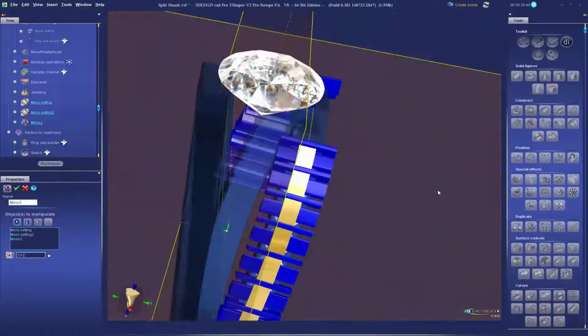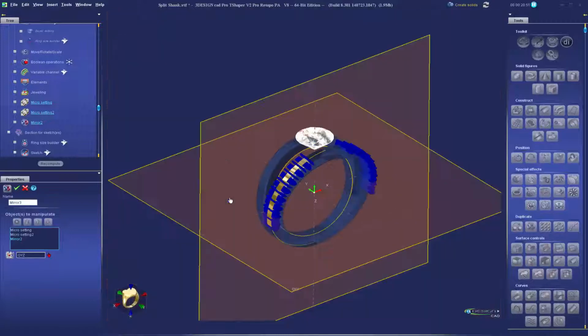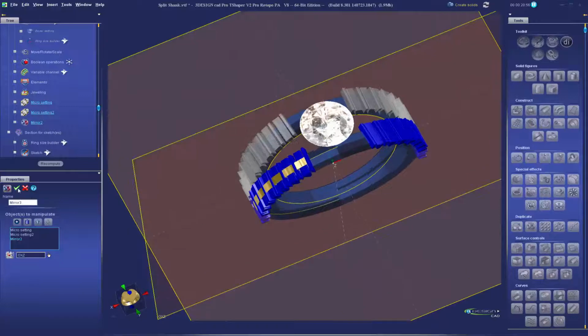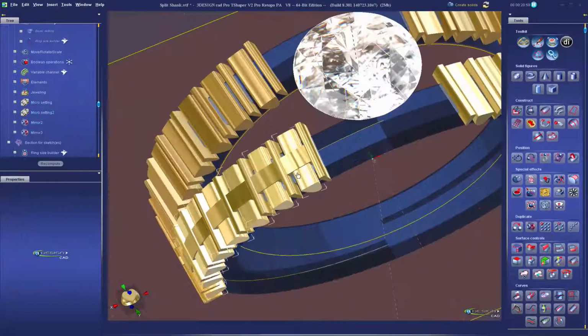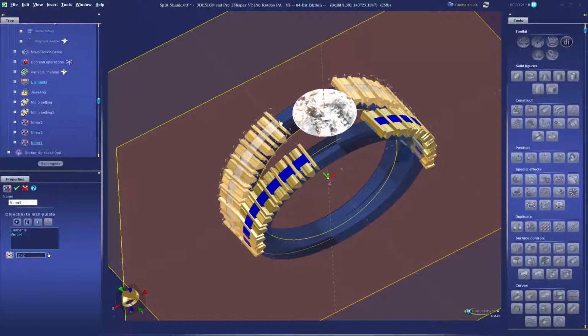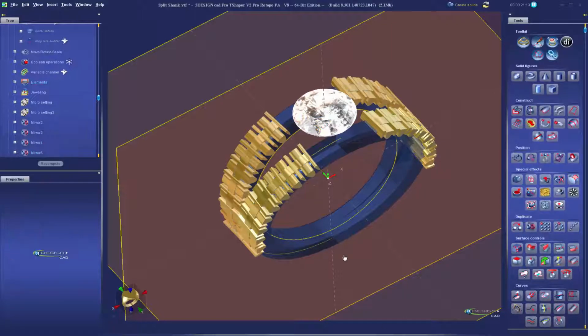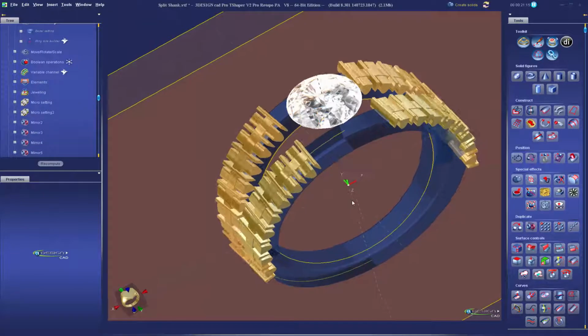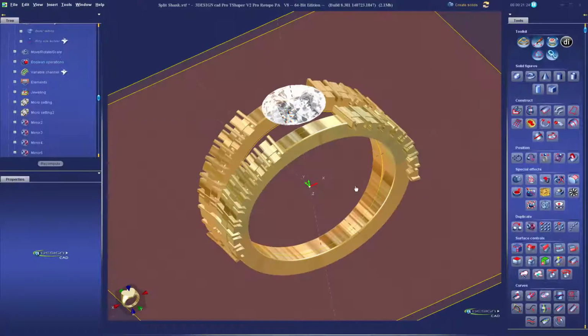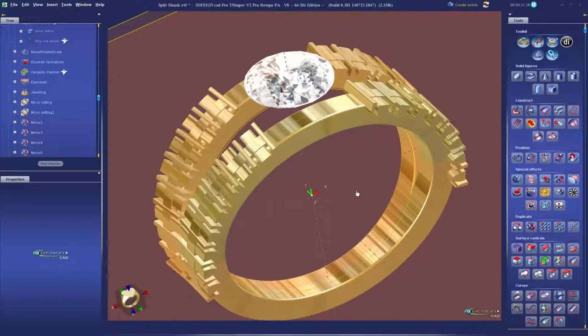Okay. If it doesn't pick the correct plane, you may have to change the plane here. That's the OXZ. We should see something like that. Validate. Okay. And we'll do the same thing with my center cut using that channel piece. Mirror to one side, select both, mirror to the other side. That time it picked the right plane, so good to go. And unfreeze our Boolean operation, that's the split shank. And you're ready to start cutting away those slices here, those little cuts across the bands.